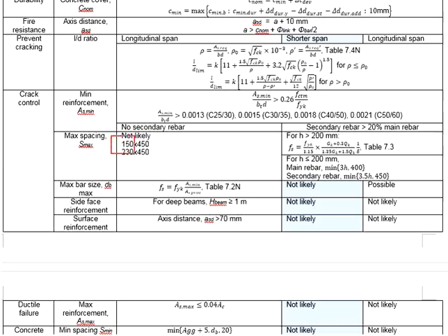When the beam's width is relatively small, which is 150 or 230, the spacing between the reinforcement bars would be quite limited. After minusing the concrete cover, the spaces for the links, therefore, you don't really need to check for the maximum spacing when you are designing for the beam. You may check the maximum spacing for the beam. Normally, it will end up passing the maximum spacing.